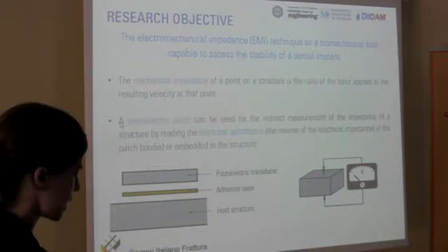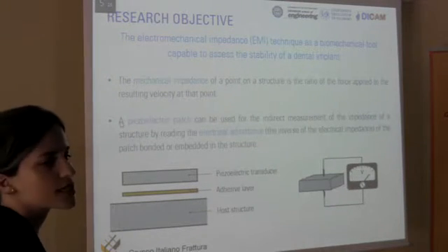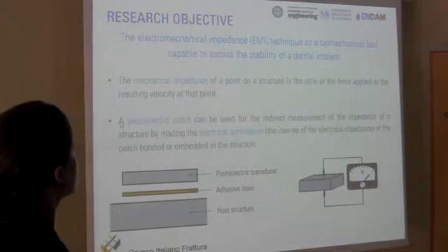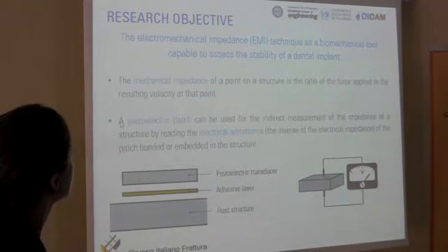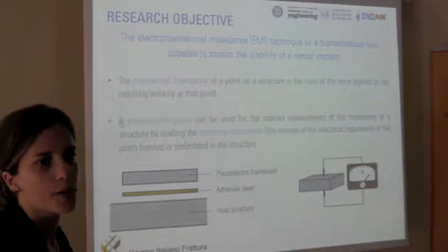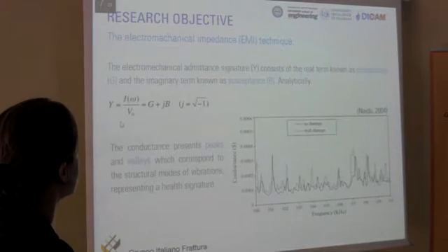When an electric voltage is applied to the transducer, it causes structural excitation to the area close to the transducer. So we basically want to measure the mechanical impedance of the host structure by reading the electrical properties of the transducer, in particular the electrical admittance.